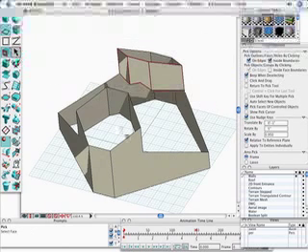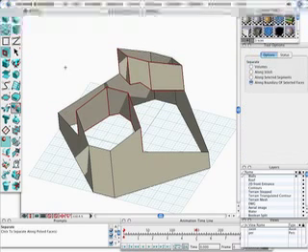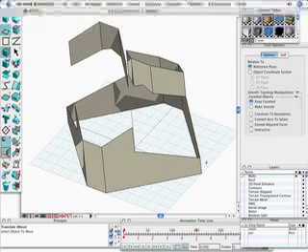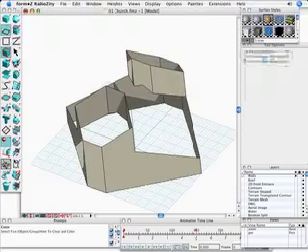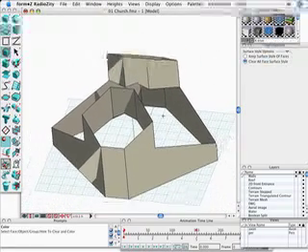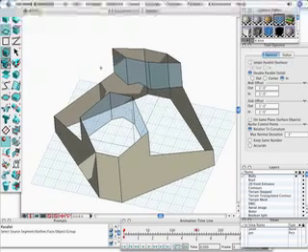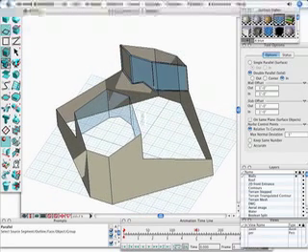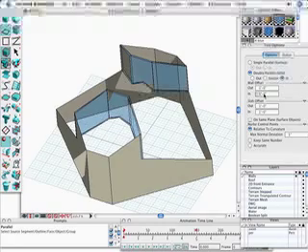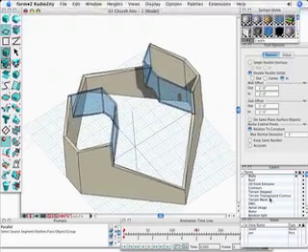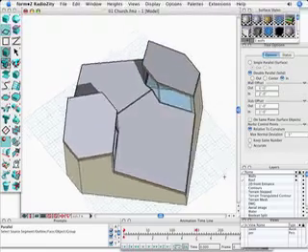Now if we want light to come inside the towers, we can take these faces and we can use the Separate tool to separate those so they become separate objects. And if these are glass panels, we can assign a transparent surface style color. And these are all paper thin surfaces, so we can use the Parallel tool, give it the offset thickness that we want, and convert that paper thin surface into a solid object of any thickness that we want. So we can convert from a solid to a surface, then back into a solid object.